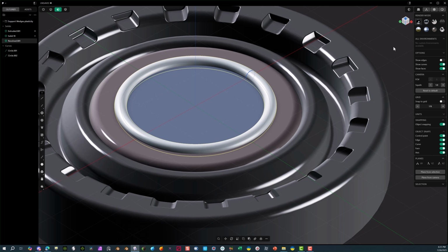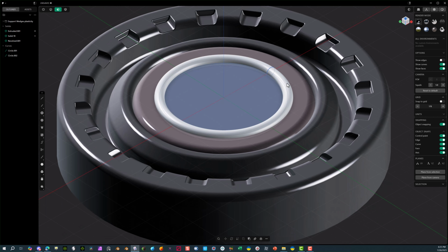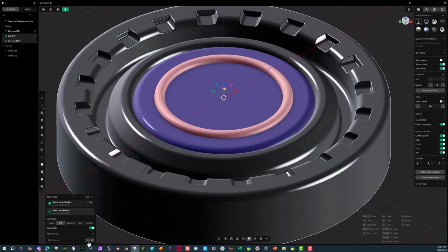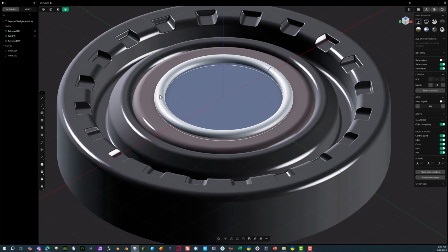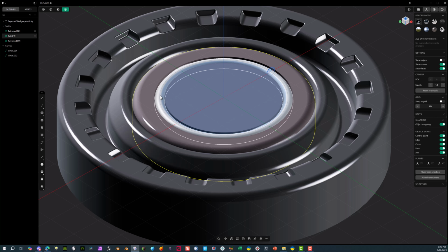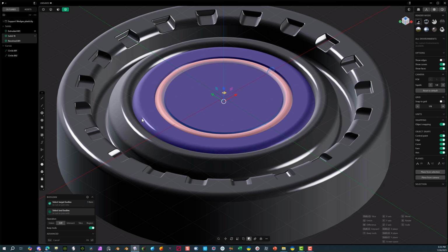That's simple, right? Now what I can do with this is I can go here and I could just cut this with this. So go ahead and hit Shift. We're going to do Q key, and we're going to keep tool. The reason for that is so we can actually continue to manipulate this with this. I'm going to hit this again, G key. I'm going to bring it down a little bit more. And this time I'm going to do the same thing. I'm going to hit this again, Q key. It still kept its keep, which is good.